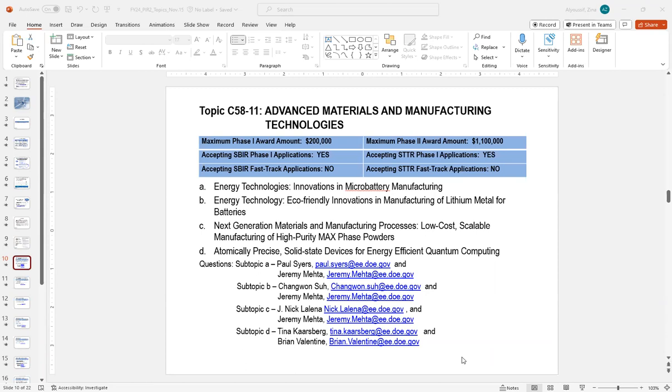If there is an affordable and scalable synthetic route with a high yield that can be developed with a high purity, the MAX powders or fabrication of MAX phases should have an ability to be produced for the market based on their unique properties, particularly the operation in high temperature, neutron radiation, oxidizing, corrosive environments, and harsh industrial applications.